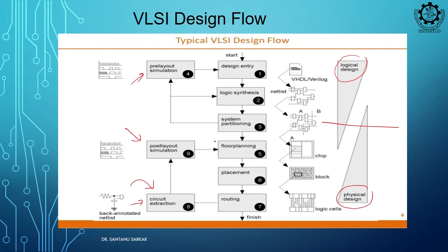In physical design, first you have floor planning, just like we do floor planning of our real estate, in silicon also you have to do planning. Your silicon area is also very costly. When you go for fabrication, generally we book an area slab wise, so we have a minimum area that we can book. So floor planning decides which portions will be placed in which position, then placement, routing.